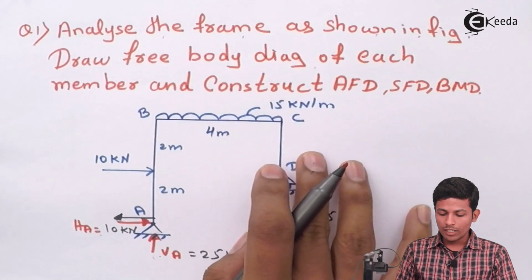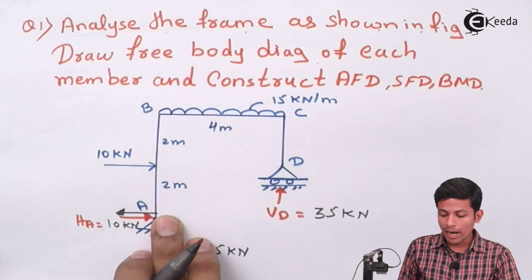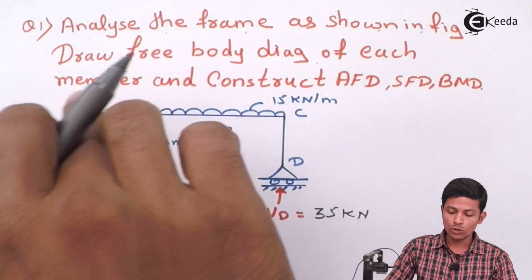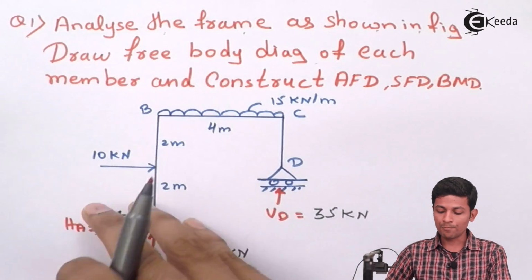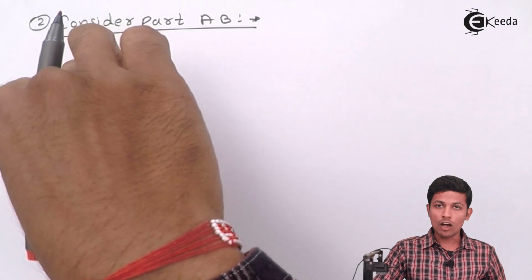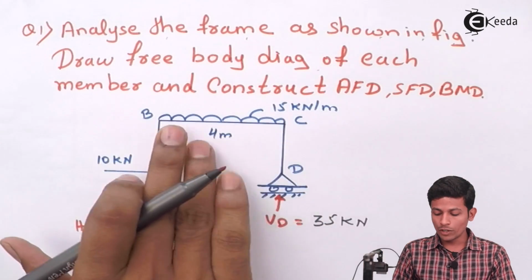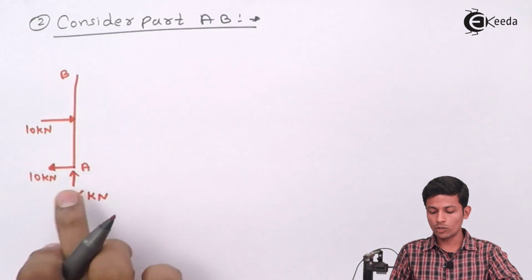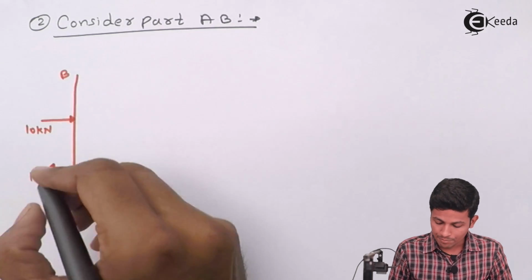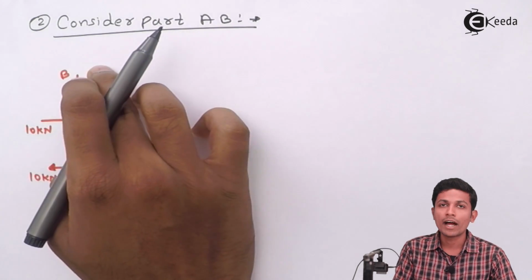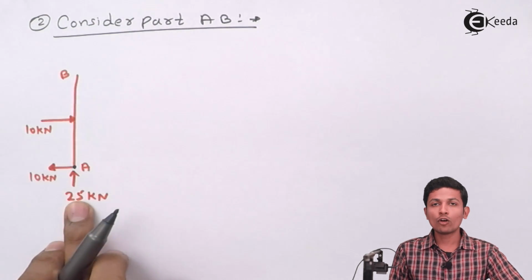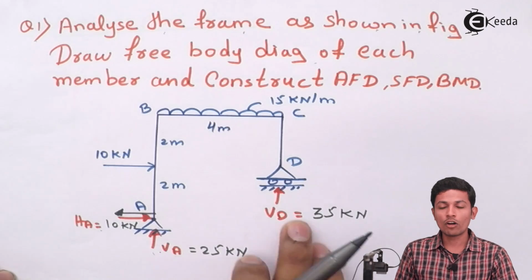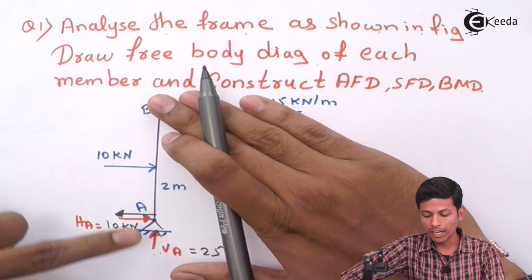Now in the exam you have to balance part A. While seeing the part of A, you cut the part over B, we cut the part AB, so separate the AB part as here. We have drawn the AB part over here. Now what will we do? You don't have to remember these things, you have to neglect the remaining part BCA as you all know here. Now we have to balance the B part. While seeing A, we will not look at the original diagram where this UDL is there, this load is there. Always neglect this part.